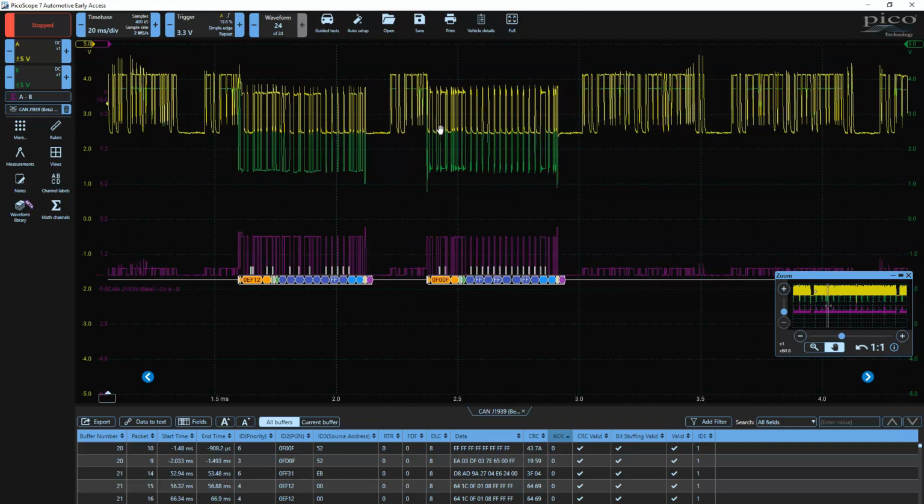It may still be working correctly because it's able to see the speed command, but the device, in this case the engine controller that's controlling it, might be complaining that it does not see the messages from the fuel pump. However, the fuel pump is apparently seeing my messages. So whatever it does, there would be something in the software of the engine controller as to what it does when it doesn't detect that the fuel pump is present.